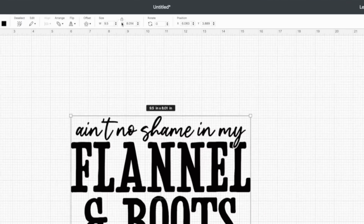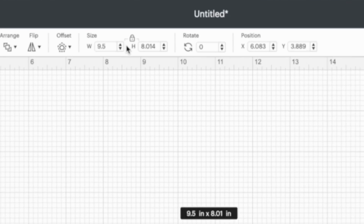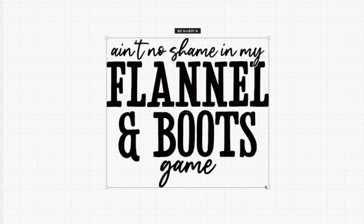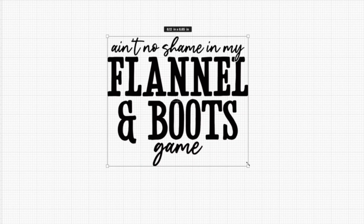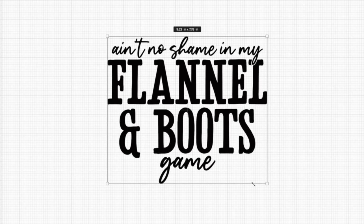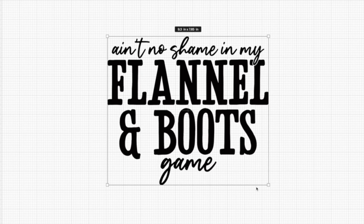and that is gonna go ahead and resize that for us. One thing that you always wanna keep in mind is make sure that this lock is locked when you go to resize that. If it's not, it'll distort. Just undo it and do it again. So I've got 9.5 by 8 inches. So I'm happy with this. We're good to go. Another way to size this is if you simply grab and hold right here, you can simply grab and hold this until you get it where you want it as well. So say I just want it right there, I'm good to go.